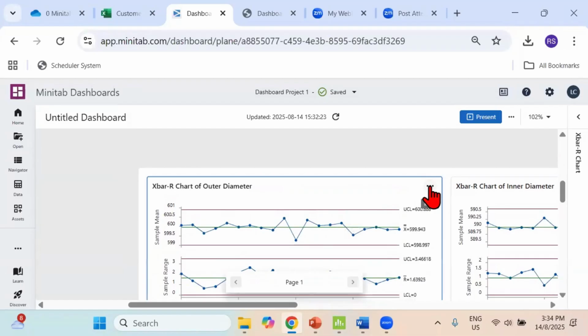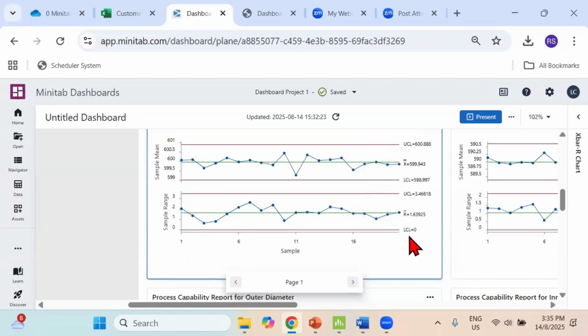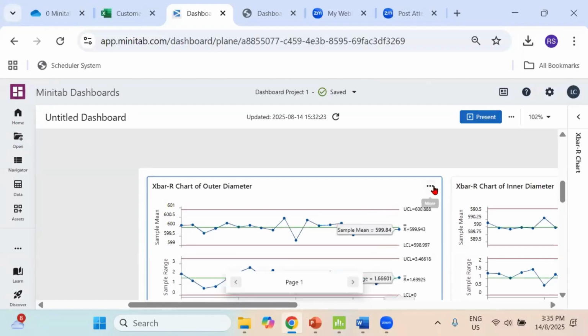Be careful that the control limit and specification limit are different items. Control limits are based on the process performance, and the spec limit is the customer requirement. And when we add the spec limit, normally we add it to the I chart. Okay, so this answers the question.